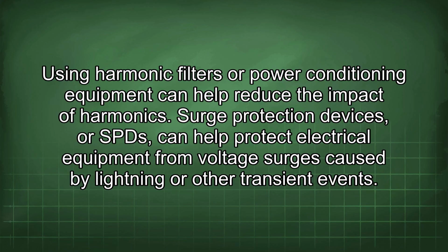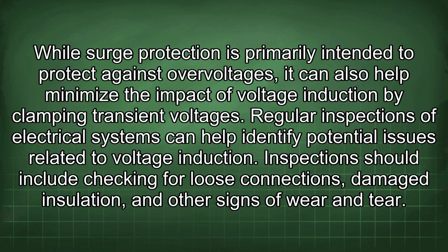Surge protection devices, or SPDs, can help protect electrical equipment from voltage surges caused by lightning or other transient events. While surge protection is primarily intended to protect against overvoltages, it can also help minimize the impact of voltage induction by clamping transient voltages. Regular inspections of electrical systems can help identify potential issues related to voltage induction.